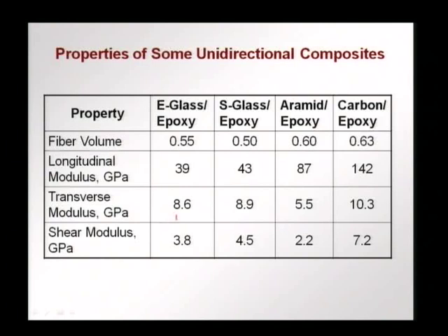This is the transverse modulus, that is in the direction perpendicular to the main fibers, and you see that since we are applying tension in the other direction, the fibers are not contributing or contribute very little, because you may have some systems with bidirectional fibers, but generally we find that there is a big difference between the transverse values and the longitudinal values.